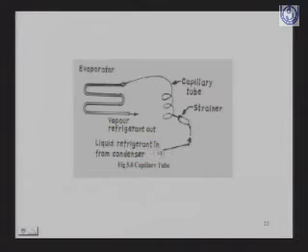expansion device. Now the expansion device mainly converts the high pressure refrigerant to low pressure. So from the condenser, the high pressure liquid is coming through the strainer. When it flows through the capillary, with the passage of time, with the orifice, what happens? This is changed into low pressure liquid, which enters the evaporator.